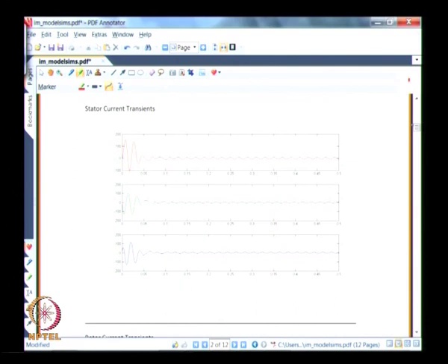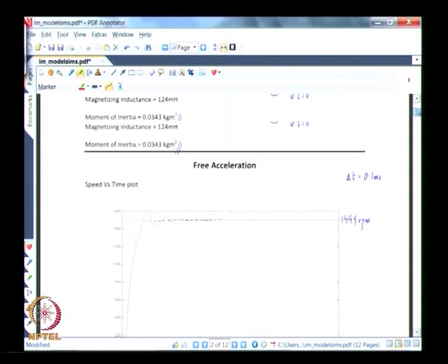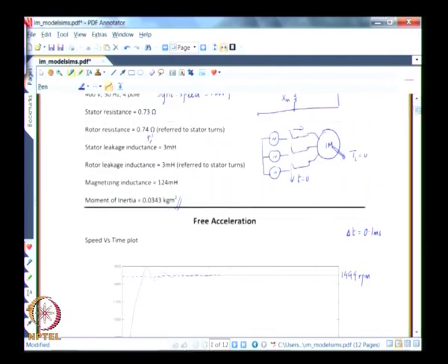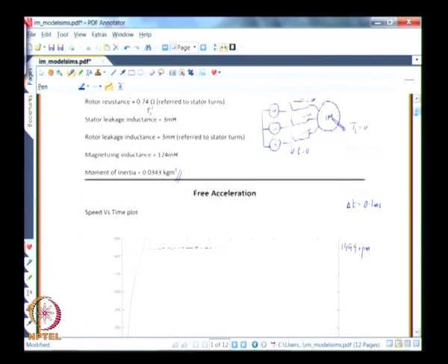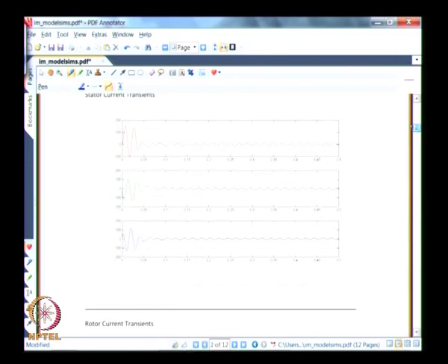Now here you see how the input flow of current to the machine is. These three plots show the phase currents of the machine, IA, IB and IC. Now you see here that the steady current drawn is quite small. In fact, if you had zoomed in to this, I have not shown you that plot, but if you look at this figure, this steady current, which is a small number, is about 8.1 ampere peak, and the waveform is sinusoidal.